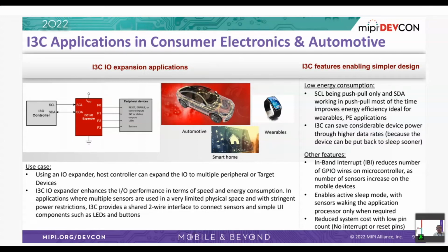So with the SCL now being push-pull and the system able to start directly in I3C mode, a system built purely of I3C devices can not only increase the communication speed, but also reduce the time for which the target sensors are in active condition. So the sensor can now play a better part in managing the overall battery life by being in a standby state with a lesser amount of communication for the same amount of data.